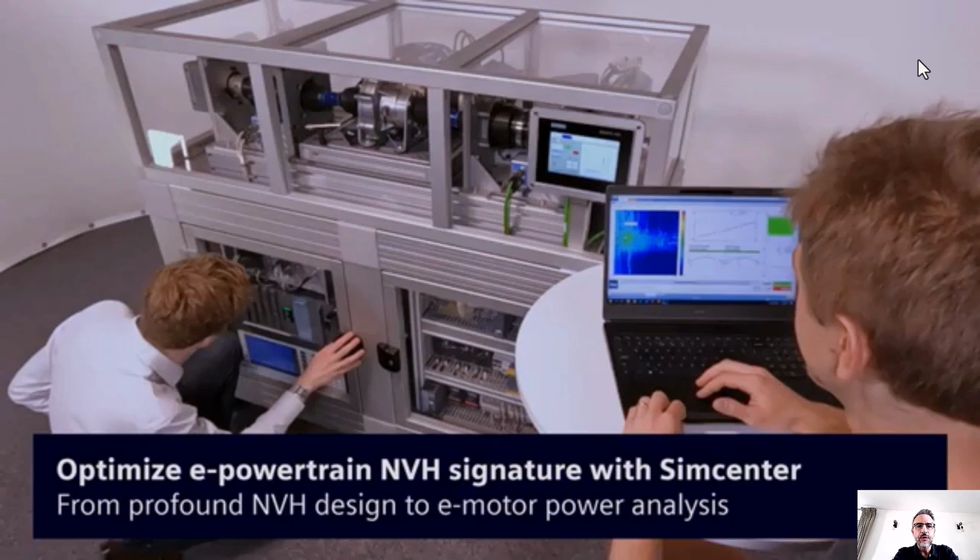You can see here above the eDrive itself, the physical eDrive, which is driven by a motor, and then below you have a real-time computer which has a real-time model of the vehicle running. So the idea is that with this we are able to represent real driving scenarios and to test the NVH of the gearbox along with realistic loading conditions and scenarios.